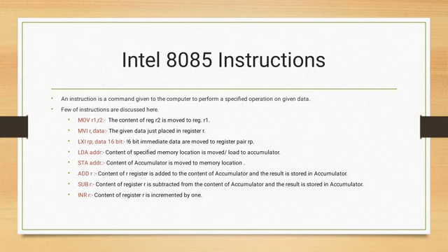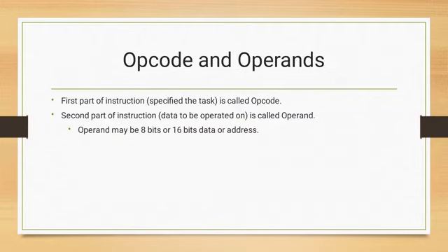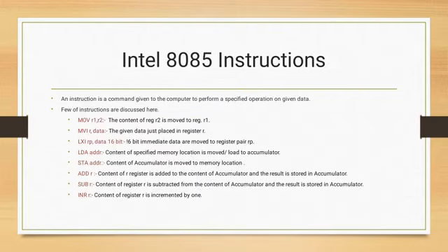The next one is INR. The INR instruction is used if we want to increment some values. In that case we will use the INR instruction. INR R means the content of register R is incremented by 1. Thank you.